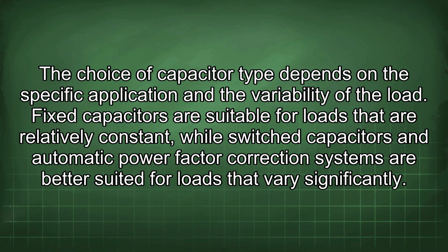The choice of capacitor type depends on the specific application and the variability of the load. Fixed capacitors are suitable for loads that are relatively constant, while switched capacitors and automatic power factor correction systems are better suited for loads that vary significantly.